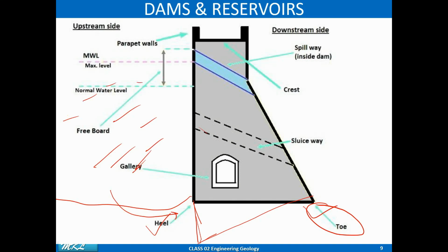As a civil engineering student or a civil engineering professional, you should control the seepage. You should have a design that controls the seepage. You should have some remedial measures which can control the seepage, and I will later discuss how seepage can create a problem in dam stability.